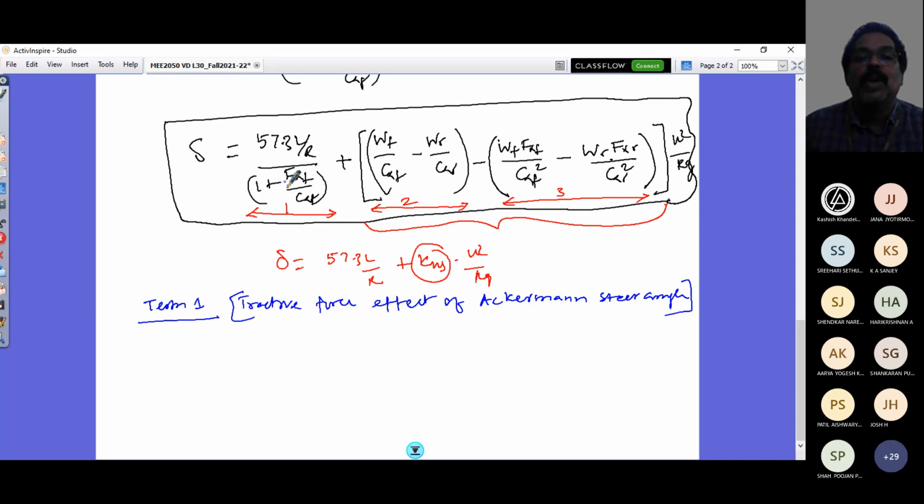Now you can see, if I have more drive force, if I do accelerate, what would happen? The Ackermann steering angle originally there in steady state motion gets influenced, how? If tractive force is positive, FXF positive means it refers to traction applied. So this term is getting added with this one. So this denominator is going to be more than 1, and this is going to reduce the Ackermann steering angle. So there will be a reduction in the Ackermann steering angle. So if FXF is positive, drive force applied on the front wheel drive, if I have front wheel drive alone, I'll have this term, right?